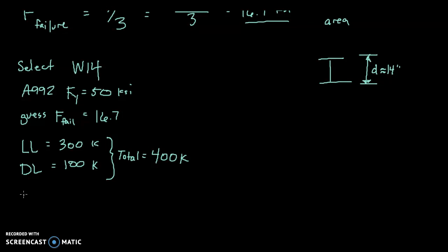That's all that's important. And we have an effective length, actually not just unbraced length, but effective length, KL. So the problem statement has already multiplied the length of the column by K for us. That's going to be 26 feet. Now, it's commonly more convenient to use inches as our unit of length. So 26 times 12 is 312 inches.